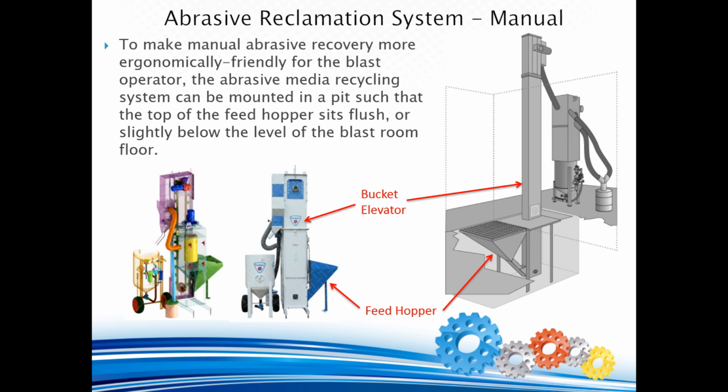With a pit-mounted recovery system, extra care must be taken to ensure that the pit always stays dry with either no possibility of water entry or adequate provisions made for drainage to always keep the pit dry. Any ingress of water into the abrasive reclamation system will cause equipment failure and loss of production time.